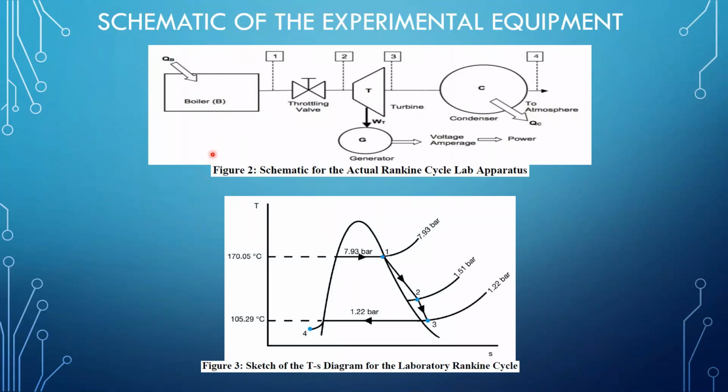Now this helps improve the overall thermal efficiency of the cycle, and that's why this is usually done in larger plant applications. However, if you look on page 5 of your lab scripts, you would see that due to the ultra small scale of this apparatus, returning the condensate back to the boiler is quite impractical, which is why it's not done in this lab apparatus, and the condensate is released to the atmosphere in the gaseous form, right?